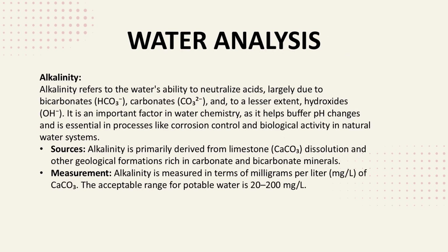Let's move on to water analysis, starting with alkalinity. Alkalinity measures water's ability to neutralize acids, which is essential in various processes like corrosion control and maintaining pH stability in natural water systems. Sources of alkalinity. Alkalinity primarily comes from limestone and other carbonate-rich geological formations. It is measured in milligrams per liter of CaCO3. For potable water, the acceptable range is 20 to 200 mg/L.